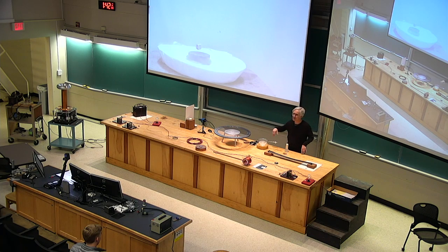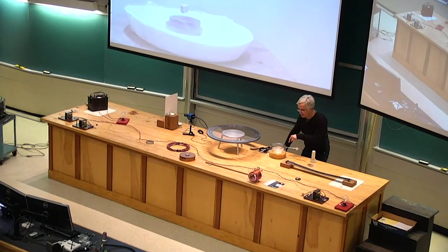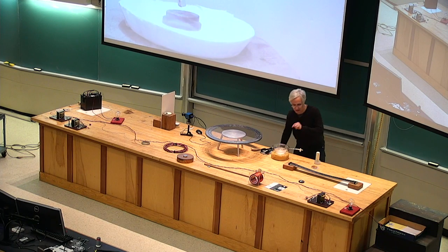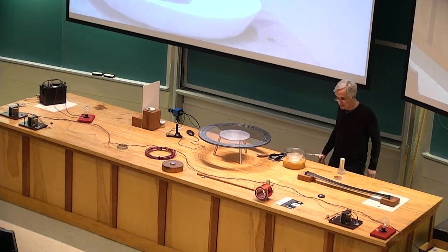And the container, incidentally, is basically a thermos bottle. It's a double-walled glass container with a vacuum in between. So there's no thermal contact between the inside and the outside. It's difficult for heat to flow in and boil away the nitrogen. What else? This tends to accumulate a layer of cold air above it, which also sort of buffers it against heat. It does exchange heat by thermal radiation. And in a proper thermos bottle, we would have mirrored surfaces in there to try to prevent the exchange of heat by thermal radiation.